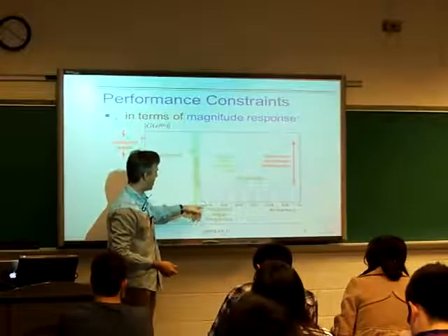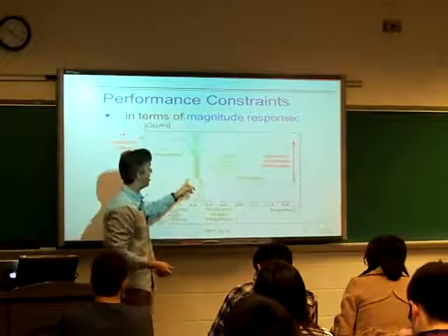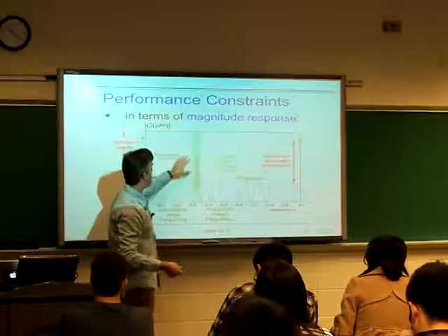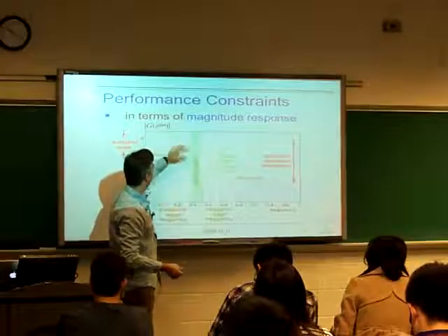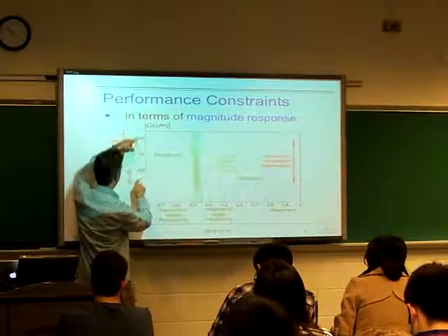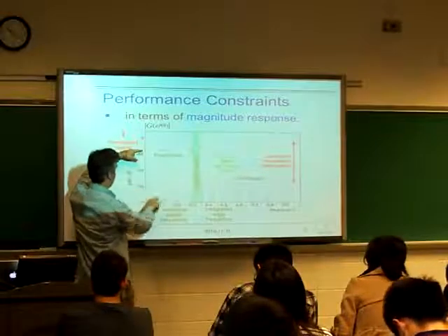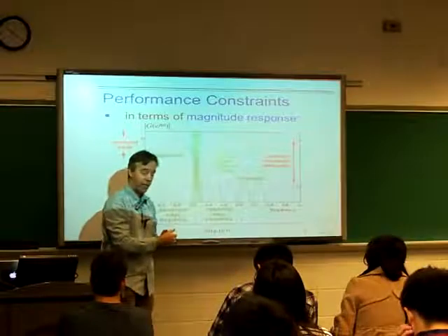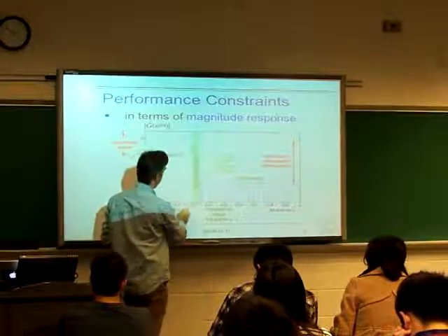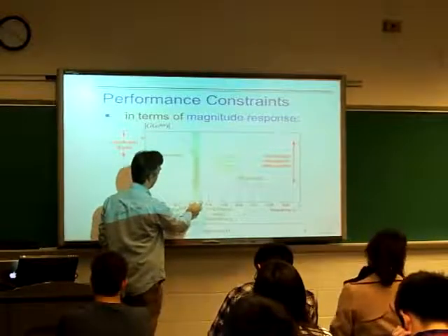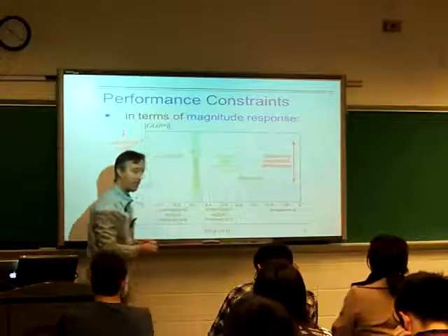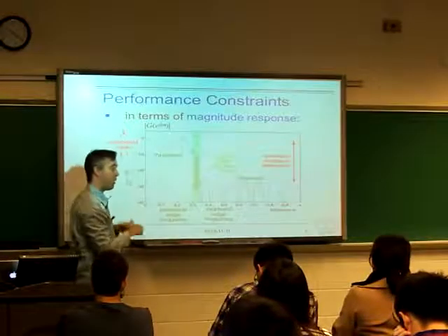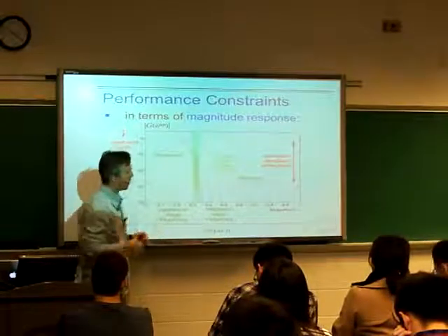It's got these asymptotes down here because we plot it against a log, but it's going to be some continuous function, so there's a gap between our worst pass band gain and our largest stop band gain, so it has to have some frequencies in order to make that transition. And so we have separate pass band edge and stop band edge, and in between them we have a transition band, a range of frequencies where we don't constrain the gain at all.